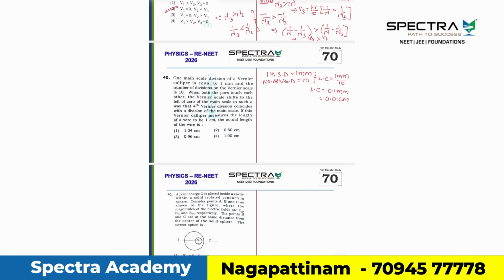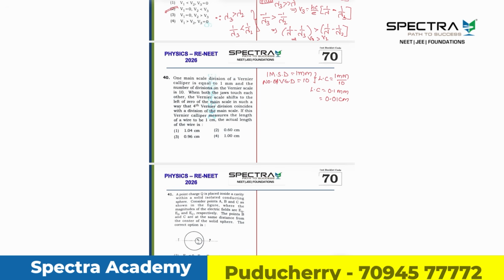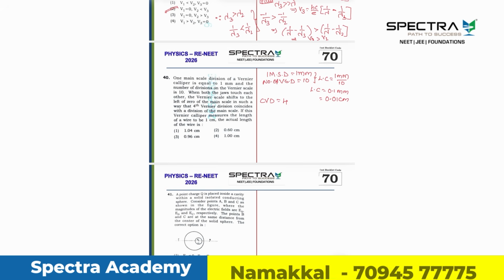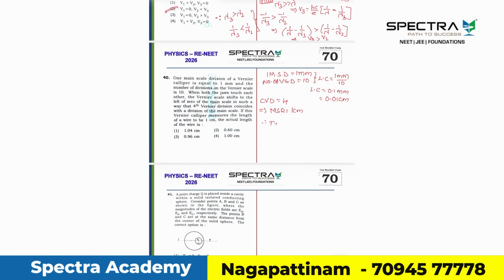Understood? Not only that, they are saying the vernier scale shifts to the left of 0 of the main scale in such a way that the fourth vernier division coincides with a division of the main scale. That means the coinciding vernier division is equal to 4. Not only that, it measures 1 centimeter, which implies the main scale reading is given as 1 centimeter. Now they're asking what is the actual length of the reading.